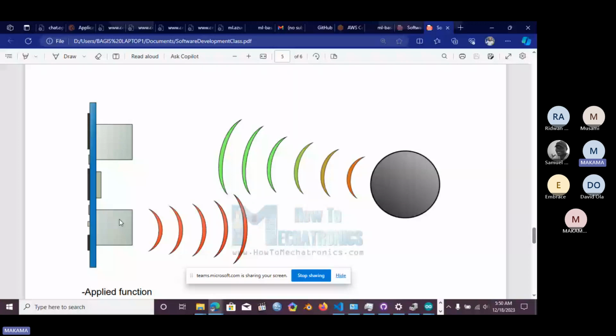So what happens if it doesn't reach any obstacle for a certain length? Let's say for kilometers, on an open road without any obstacle. What will happen is that the signal has its own limit. The moment it reaches that limit, for this prototype, this mini project sensor, because it's a small sensor, it can only reach up to a maximum of 200 centimeters. You see, very small, right?